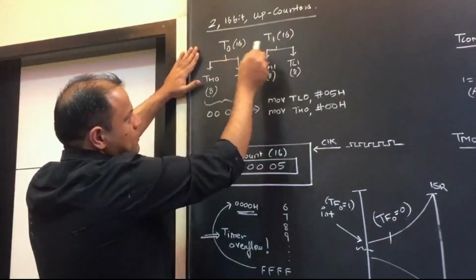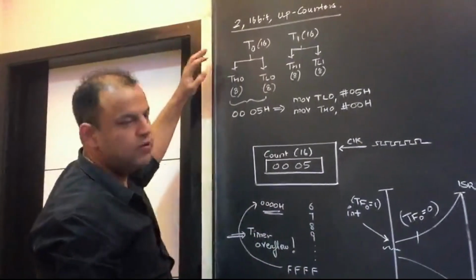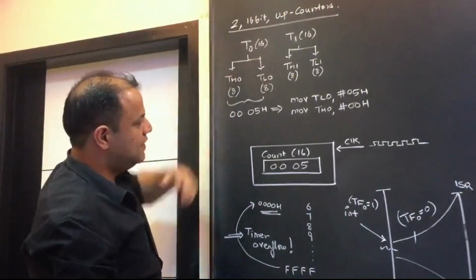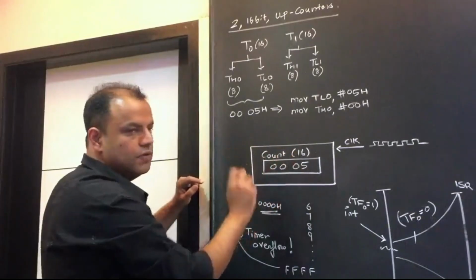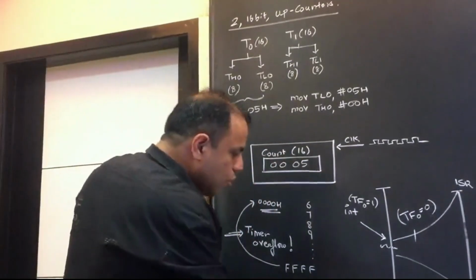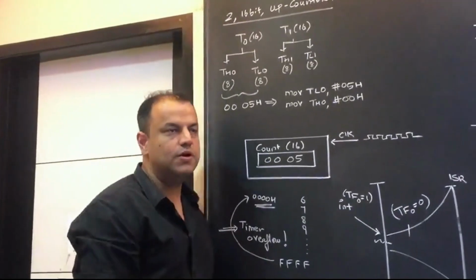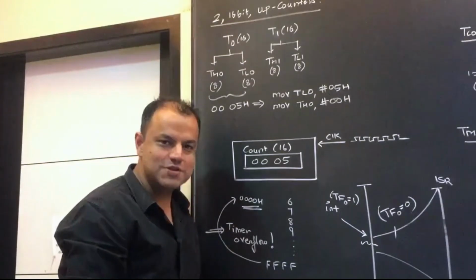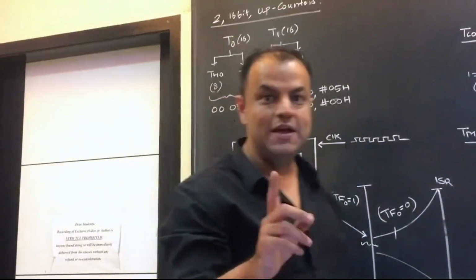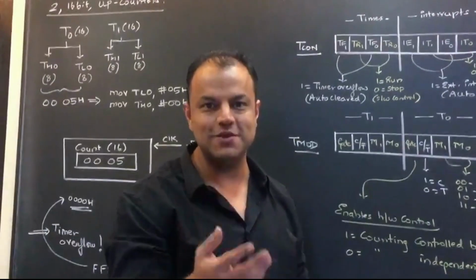So these are your two timers. They are identical. You can study any one timer; the other does the same thing. So let's look at timer 0. The first thing, as I said, is we have to load a count. The count will be a 16-bit number. To hold the count, we will need a register. That register will be an SFR. SFR stands for Special Function Register. So you need some special register to hold this count.